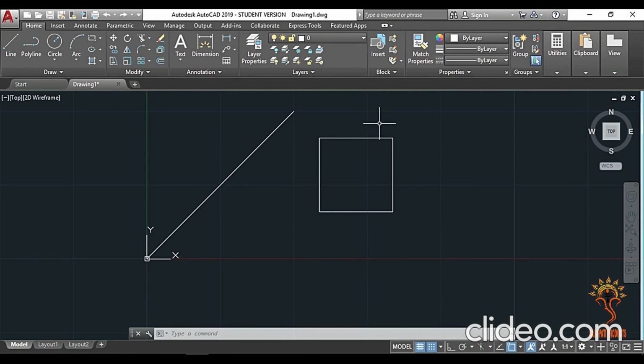Now with this we have ended the coordinate entry. There are other types of entries which we will learn now, and regarding this we'll have assignments on the coordinate entry. In the polar entry, we generally have the length, say for line, we have the length of the line and the angle at which the line is to be drawn.